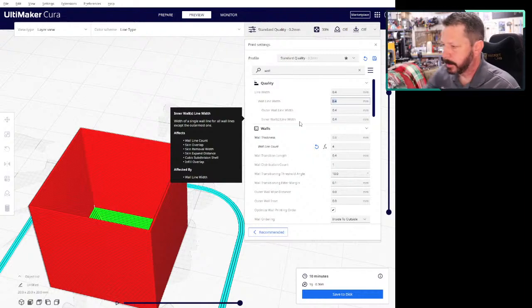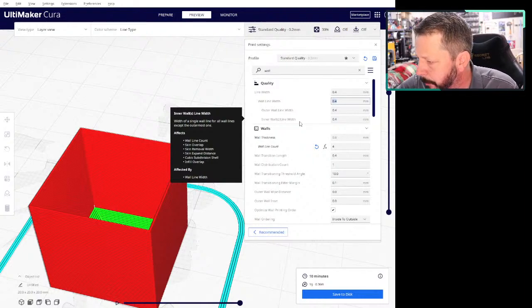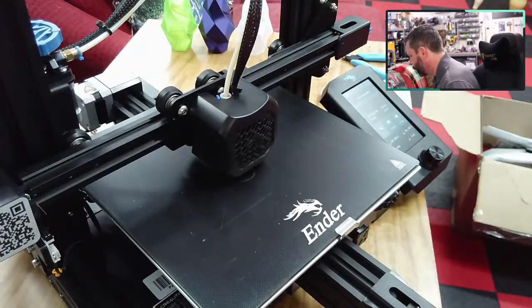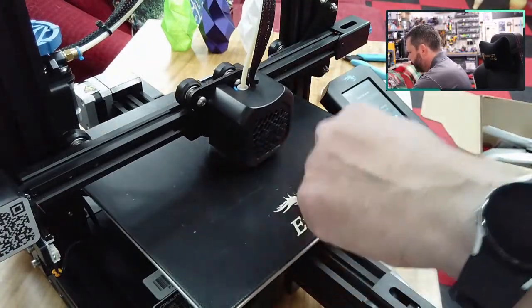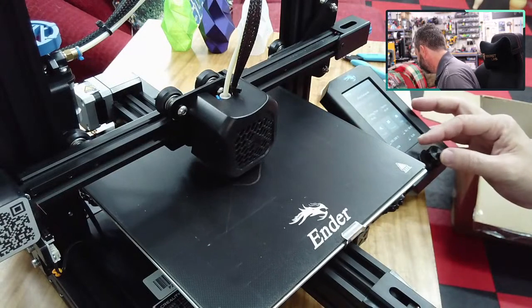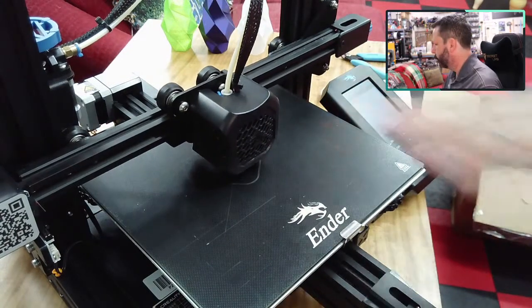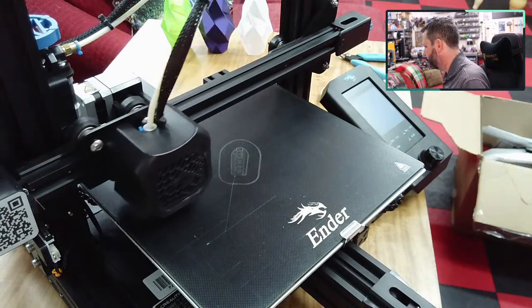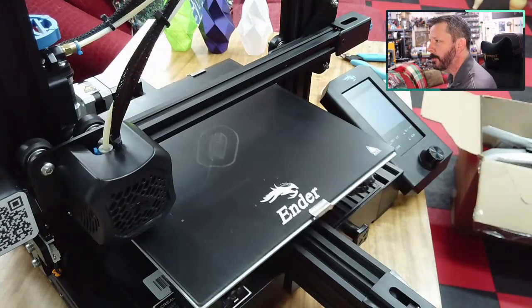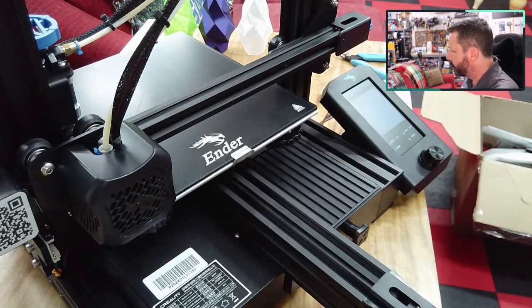All right, here's some troubleshooting right now because we don't have any filament coming out of our printer. It didn't do the purge line over here. It didn't do any of the skirt. So I'm going to stop the print. Confirm that. It's going to go through an auto home, and we're going to try to see why there is no filament. There's a couple of reasons.